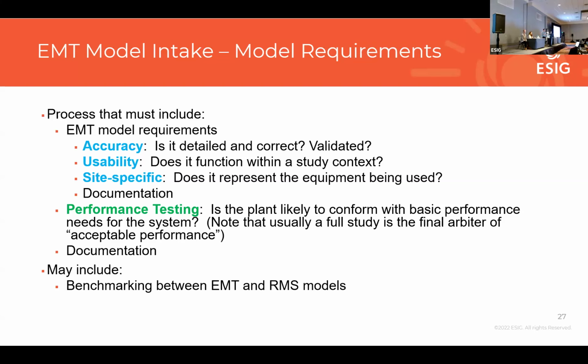We would test things like simple ride-through tests, making sure it can operate in a reasonably weak system, and that it can do voltage support and frequency support and things like that. This segment has really been expanding, and in some places has really blown up. If you look at what folks in Australia are requiring in terms of their dynamic performance acceptance testing, it's hundreds of tests. So it's very, very rigorous, and it takes a very long time.